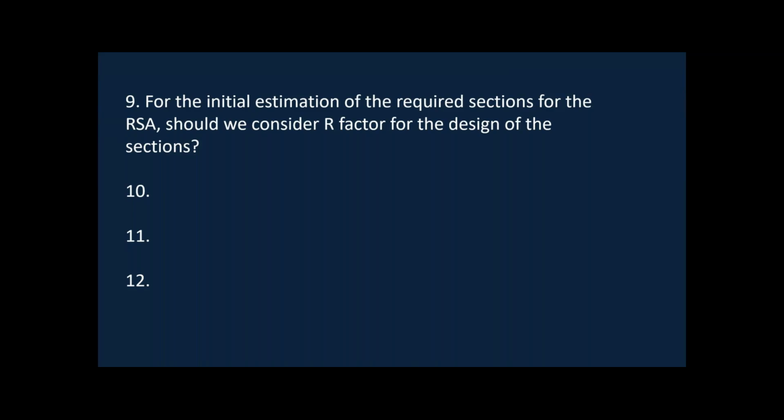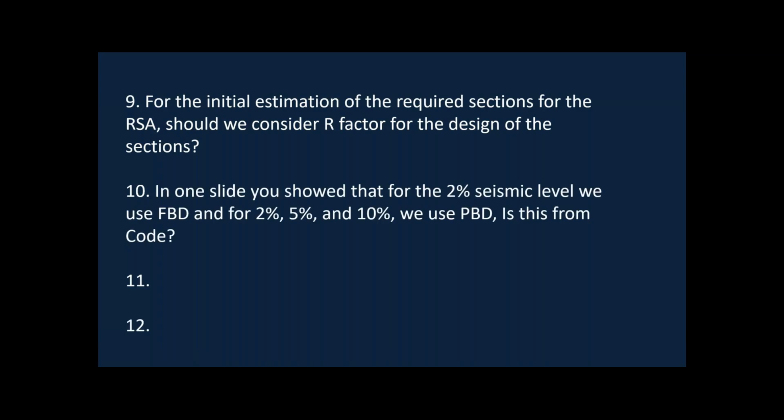So let us say the return period is very small, let's say 475 years or 10% in 50 years. For this type of structure, what we anticipate is the structure should remain serviceable and there should not be any damage. In case of performance-based design, the code asks us to evaluate the performance for the different hazard levels, depending upon the owner's criteria that they have fixed.